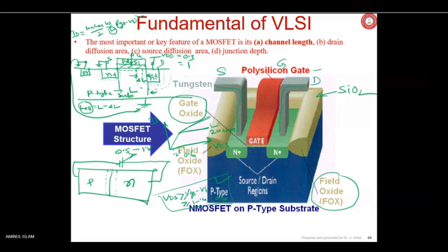This is the case of a short channel MOSFET. Yes, in the early days the depletion layer was also there, but the channel length was 20,000 nanometer, whereas your depletion layer will be very, very less, say 1 or 2 nanometer or even 5 nanometer, doesn't matter. 20,000 nanometer versus 5 nanometer is not a big deal. But today, the MOSFET channel itself is 20 nanometer or even less. Today, FETs are being made with 7 nanometer channel length.